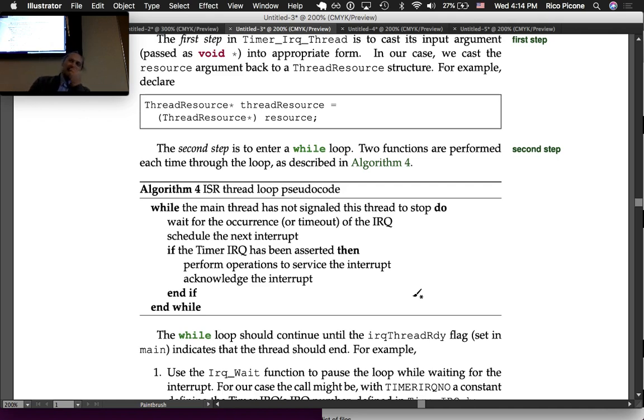Right. If it times out, it will just send a signal to stop receiving the interrupt. So say it doesn't return it. Say it's just like the ball you dropped, and if you miss it, you miss it. Then the IRQ wait on the next time would just be waiting until it timed out, and then it would go back through the loop, and it would wait until it timed out, and it would just continue waiting until it timed out.